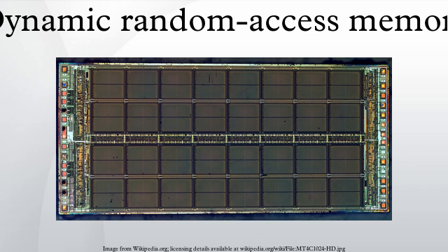Common DRAM modules. Common DRAM packages as illustrated to the right, from top to bottom: DIP 16-pin, SIPP 30-pin, SIMM 30-pin, SIMM 72-pin (but FPRAM is not uncommon), DIMM 168-pin, DIMM 184-pin, RIMM 184-pin (not pictured), DIMM 240-pin (not pictured).